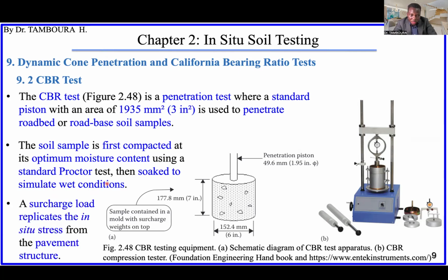Then you place a load, the surcharge load. I already explained that also, to replicate in situ stress condition from the pavement structure, before you do the pushing penetration of the piston.